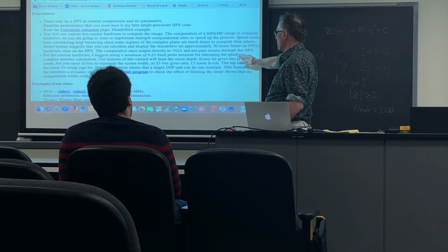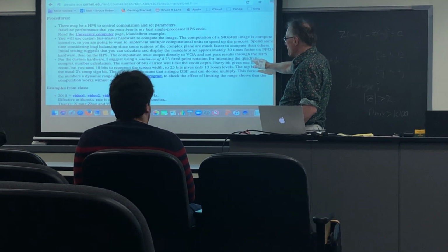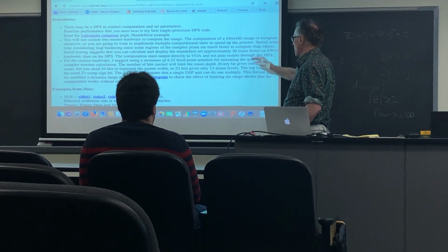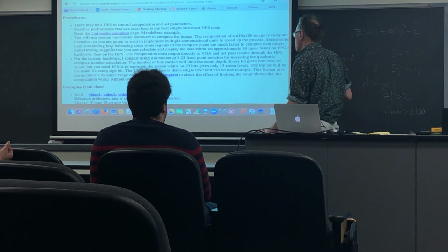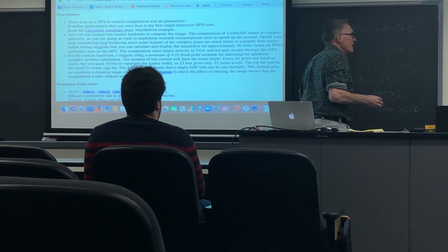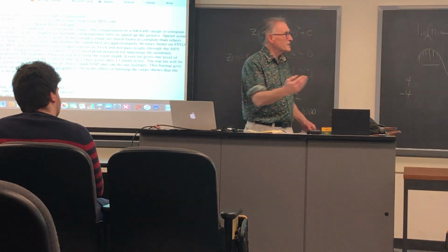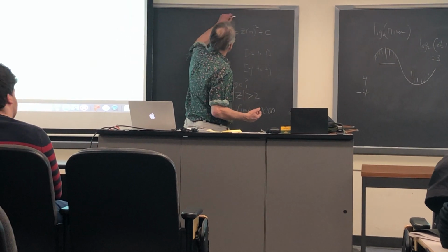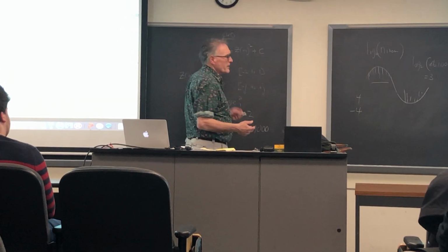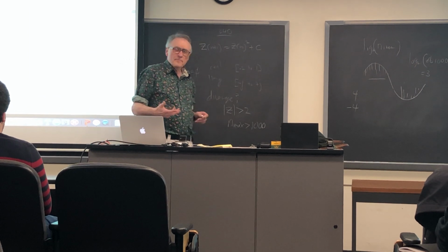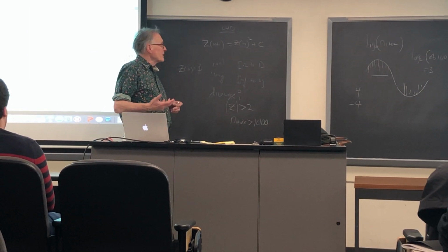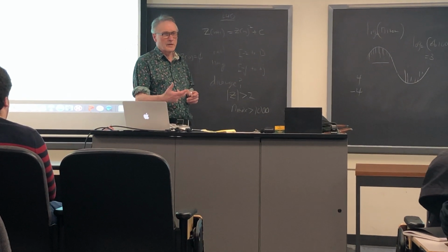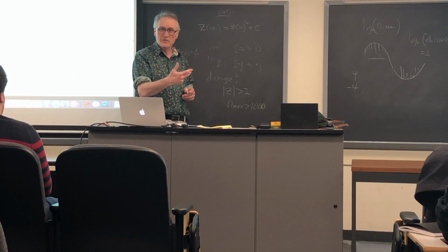So you're going to go for 4.23. Why 4.23? Well, it takes about 10 bits of the number to specify which pixel you're going to draw. Remember that the screen resolution is 640 wide. That's just a little less than 10 bits. So you're going to need about 10 bits of resolution to specify each x, and another 9 bits to specify each y.